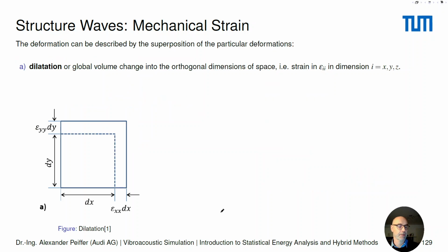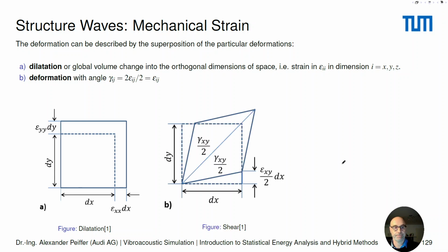Easy thing. Good. When we would like to talk about the deformation shape and the shear strains, things are a little bit more complicated. And it's a good idea to separate everything into different kinds of deformations. We start with a dilatation. That's just a simple global volume change. In 2D presentation it is a change in thickness, just adding up the normal strains multiplied by the original thickness gives us the change in volume, also called dilatation.